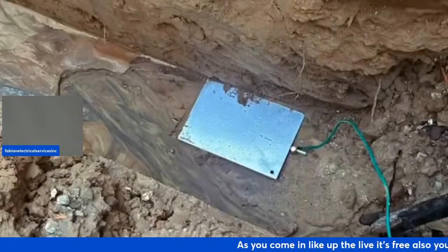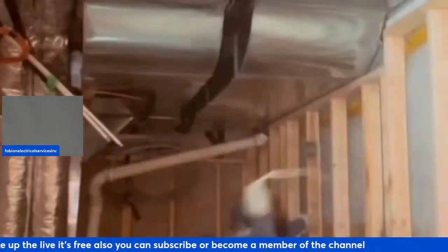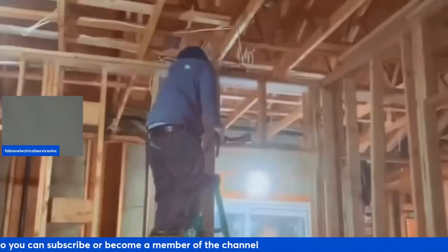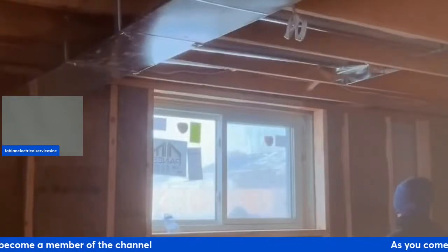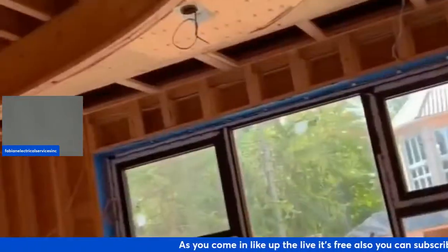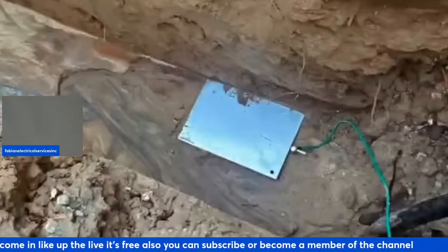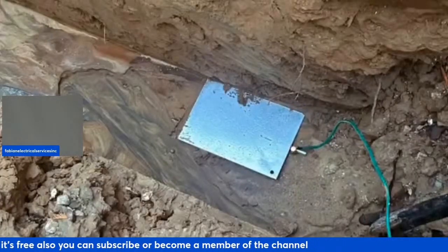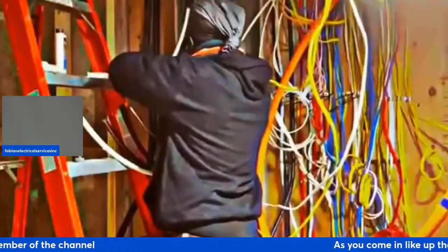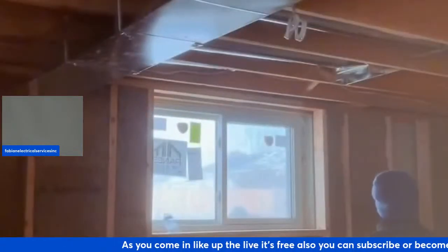It will then trip the circuit. Again, when an unsafe arc is identified, the AFCI opens its internal contacts to quickly shut off the flow of electricity to that circuit, stopping, obviously, the risk of a fire. Series arcing occurs when there's a break in a wire, causing electricity to jump across the gap, which can become very dangerous. Parallel arcing happens when electricity jumps from a damaged wire to another wire, like a neutral or ground.